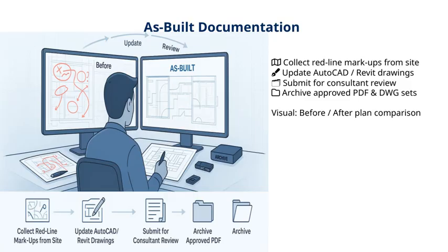All right, let's talk about as-built documentation. This is a crucial step where we collect redline markups directly from the site. These markups are essentially the updates or changes noted during construction that reflect what was actually built. Once we have these, we update our AutoCAD or Revit drawings accordingly, ensuring our digital models accurately represent the finished project. After that, we submit these updated drawings for review by the consultant, so everyone stays aligned and can verify that everything is as planned.